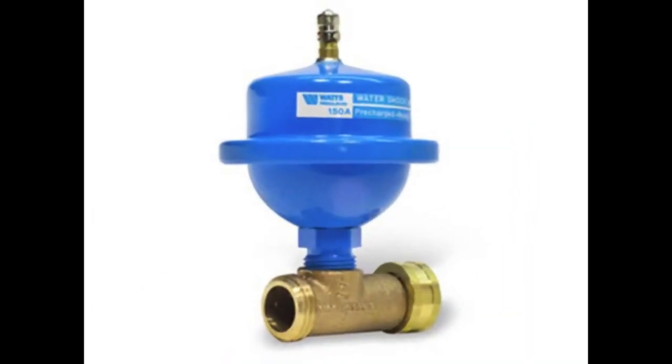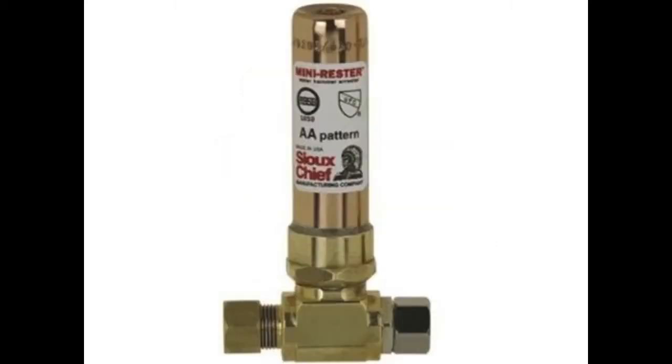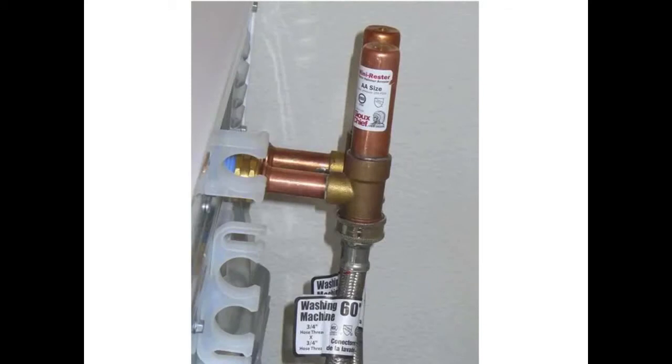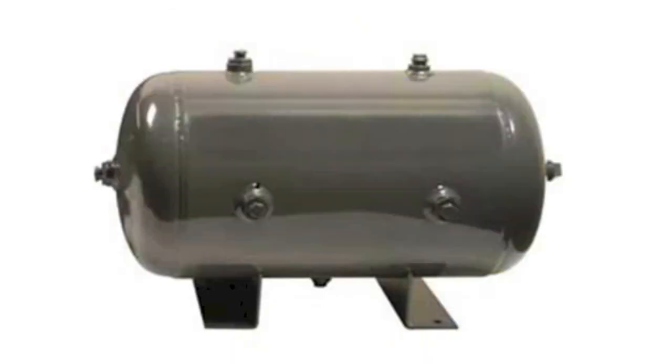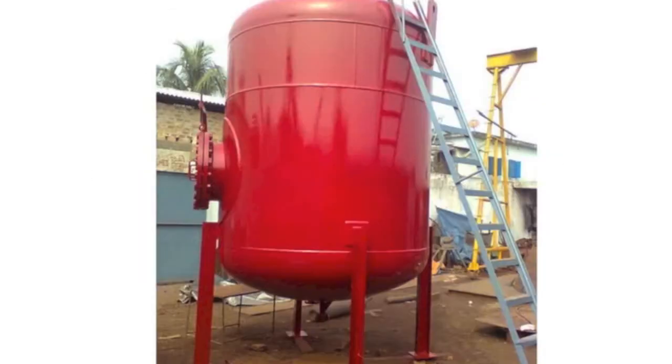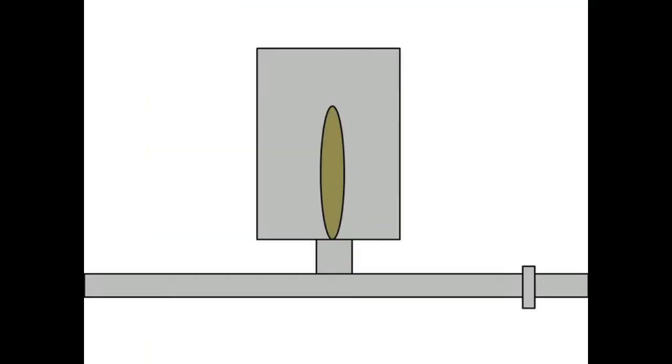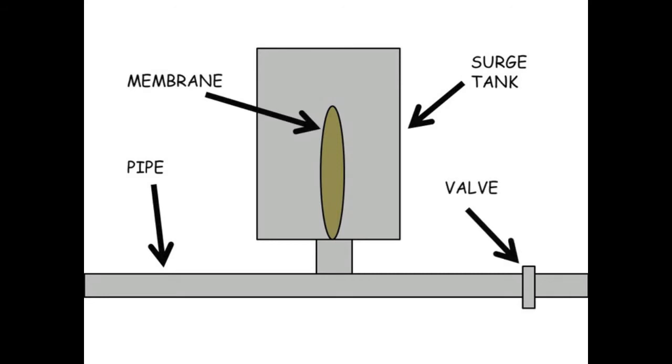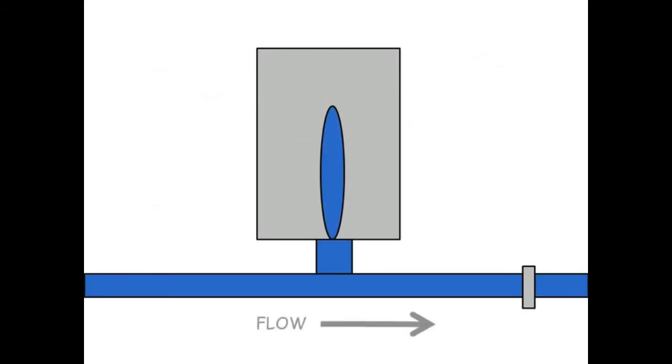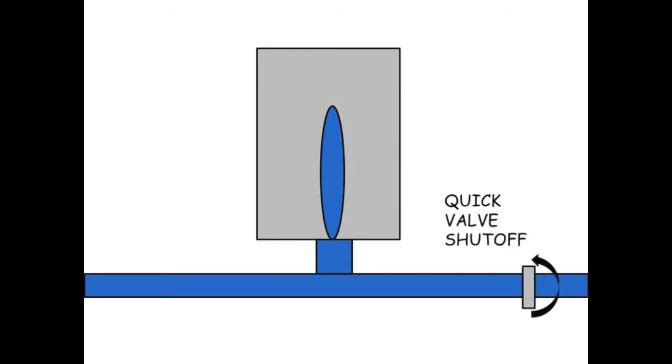So how can the water hammer effect be mitigated or prevented? Apart from increasing the time to close the valve, water hammer dampeners are mechanisms to dissipate the energy wave generated. Residential water hammer dampeners are known as water arresters. They are installed just upstream of the valve in question. Surge tanks operate on the same principle and are used in commercial applications. Surge tanks generally consist of a water-impermeable membrane inside a pressurized vessel. When the valve is shut off, the membrane will expand and fill with water. The vessel acts to reduce the amplitude of the energy waves. Notice that the expansion of the membrane is reduced with each cycle.